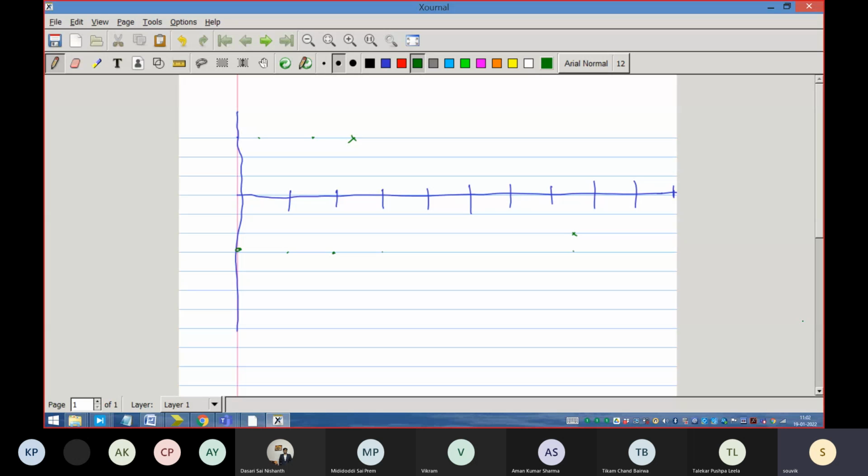That period does the average, and that's how it switches the devices of the inverter, so that from a given DC voltage, which we call VDC, if we take the average of the switched voltage, that would be equal to the sampled value of the sinusoidal voltage. Sampled value means we are sampling the sine wave in every switching period TS, and we are assuming that the switching period is very small, or switching frequency is very large compared to the frequency of the sine wave that we are trying to produce across the motor terminals.